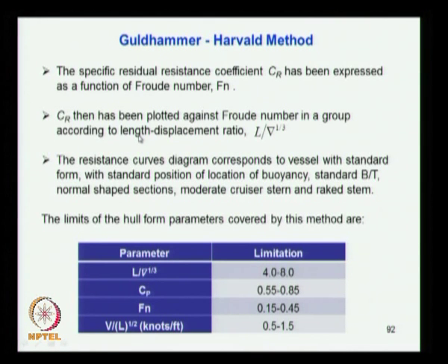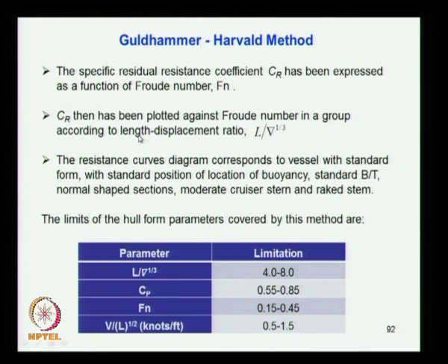So, once you have obtained the residuary resistance, you follow the ITTC formula to find the frictional resistance, and also use the form factor, from which you will get the total resistance. To that total resistance you then add correlation elements and other air and wind elements, from which you get the total resistance of the ship which you design, and from which you will be able to find out the power requirement and subsequently the power of the engine required for the ship.